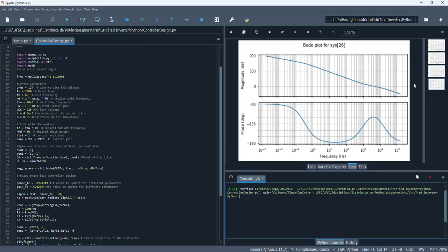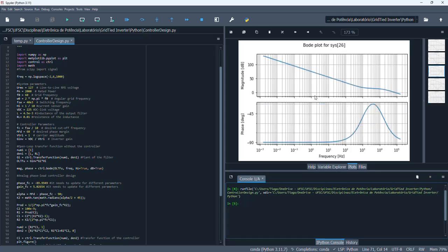If we start with the frequency response of the controller, which is this one, we can see here that the controller itself adds -90° to the system, but this is the feature that this controller holds, which is a phase lead at such frequencies that we can define later. The intention of showing you this Bode diagram is to show this kind of behavior that makes the phase go up relative to the steady state phase that we have here in this controller.